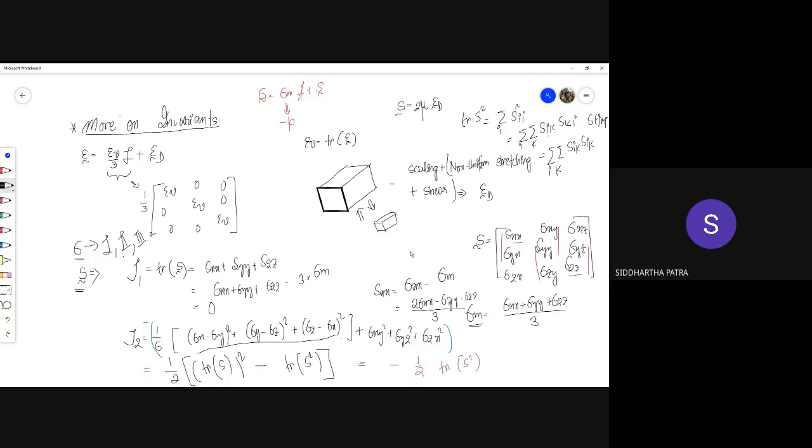What this basically means is you take individual terms of the deviatoric stress tensor, multiply with itself, and add them up. So it is essentially minus half summation over i, summation over j, S_ij S_ij. Okay, so try doing that. We have already proved that this expression right here, the J2, the sum of the determinants, turns out to be this. Look at one of the previous classes where we derived that, and that is true for any arbitrary tensor, not even symmetry. So if that is true for any arbitrary tensor, that is obviously true for the deviatoric stress tensor. So we can take help of this expression, and in that we can substitute that the trace itself is 0.